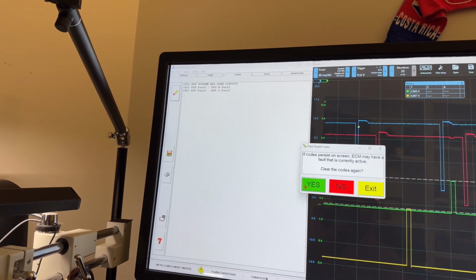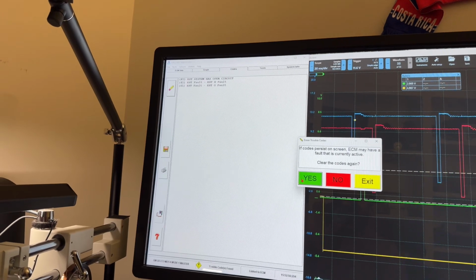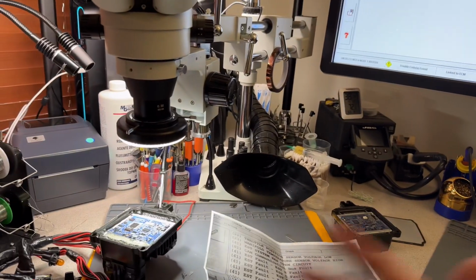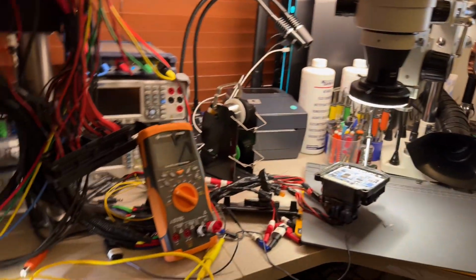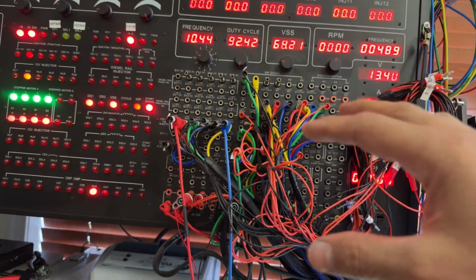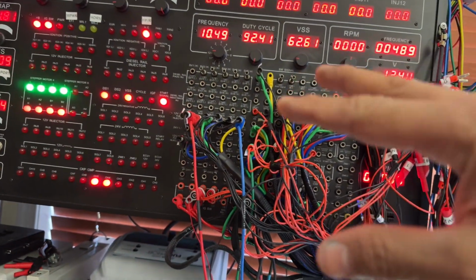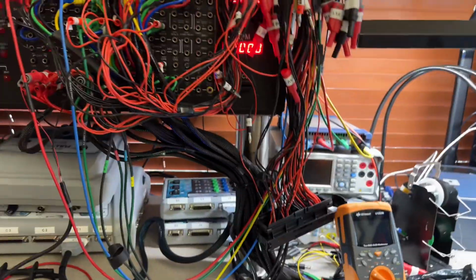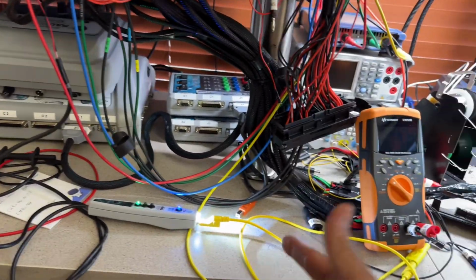All right, that's what I was expecting to see, because I have another computer here, which is an 8.1, and it's giving me the same fault. The reason is that for H and G, this simulator only has six drivers for that kind of 5 volt reference signal, so I don't have 8, I only have 6, and that's the reason I have one in here.